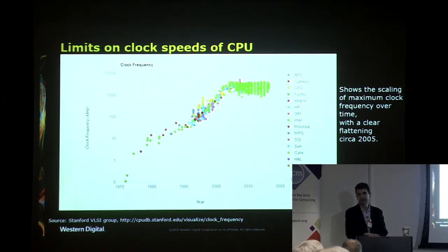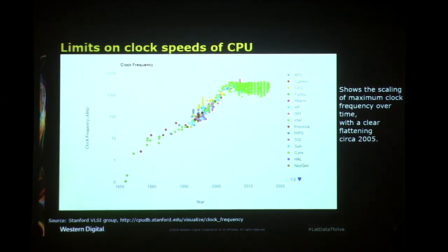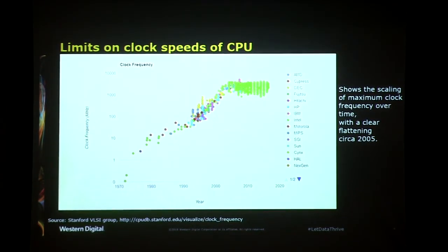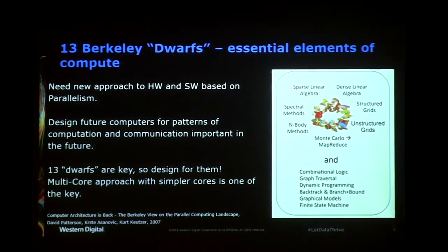The optimal thing is not necessarily to run a large number of high-performance out-of-order cores like IBM's Power 9 or Intel Xeon cores. They have a lot of capability built for software, like what I just said, out-of-order execution. If your problem reduces to matrix multiplication or vector operations, you may be better off with a larger number of smaller cores that run in order and can just really crunch those numbers, sort of like automotive DSPs. So that's the general trend when it comes to compute cores, and I'll cover this with the RISC-V architecture in particular.